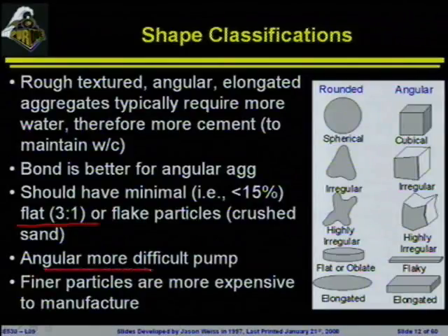The more angular the rocks, the more difficult the mixture can be to pump, so you may need to spend a little bit more time working on that. And obviously, like anything else, the finer the particle, typically the more you have to crush it, the more energy you're going to spend. The more energy that goes into crushing it, the more expensive the material is going to be.